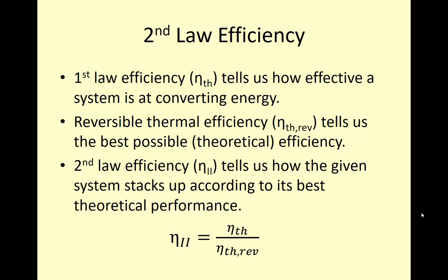second law efficiency. So this is another way of comparing systems one to another, because if you just compare thermal efficiencies, it's somewhat misleading. But if you look at a thermal efficiency and compare it to its reversible thermal efficiency, then you get a clearer view of how well your system is doing according to the second law of thermodynamics. So this second law efficiency, just dividing these two one by another, gives us that value.